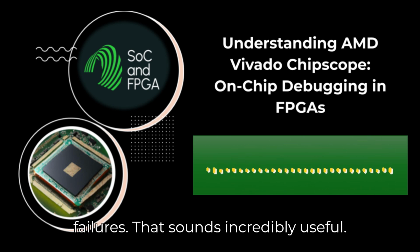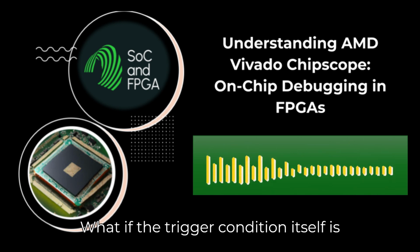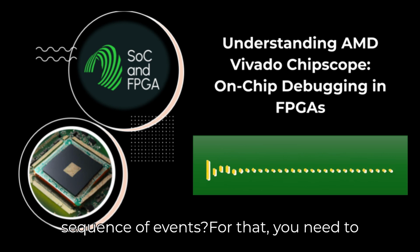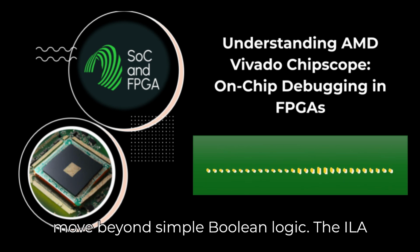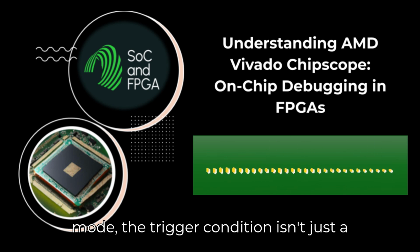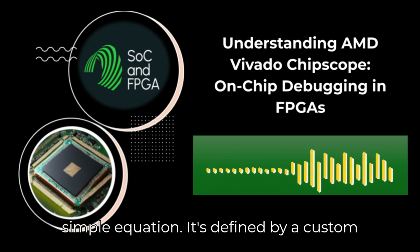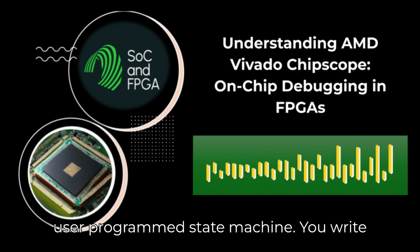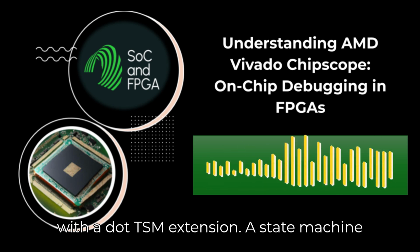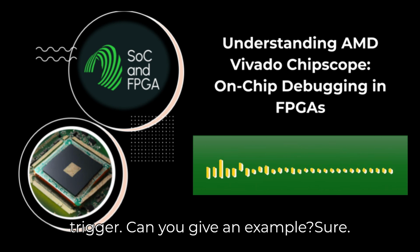That sounds incredibly useful. What if the trigger condition itself is really complicated, like it depends on a sequence of events? For that, you need to move beyond simple Boolean logic. The ILA has an advanced trigger mode. In this mode, the trigger condition isn't just a simple equation. It's defined by a custom, user-programmed state machine. You write the state machine in a simple text file with a .tsm extension. A state machine trigger. Can you give an example?